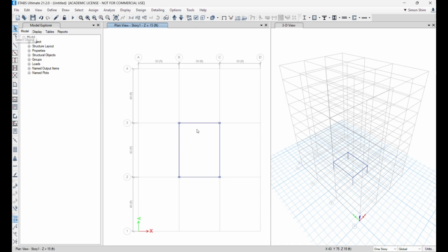Now the third one is let's add another, filler beams, because this is 30 feet and 40 feet, which we choose one direction, typically the longitudinal long direction for the filler beam. And I mentioned that spacing: typically we use 10 feet as a good starting point over 30 feet column spacing. So I'm going to click this quick draw secondary beam.